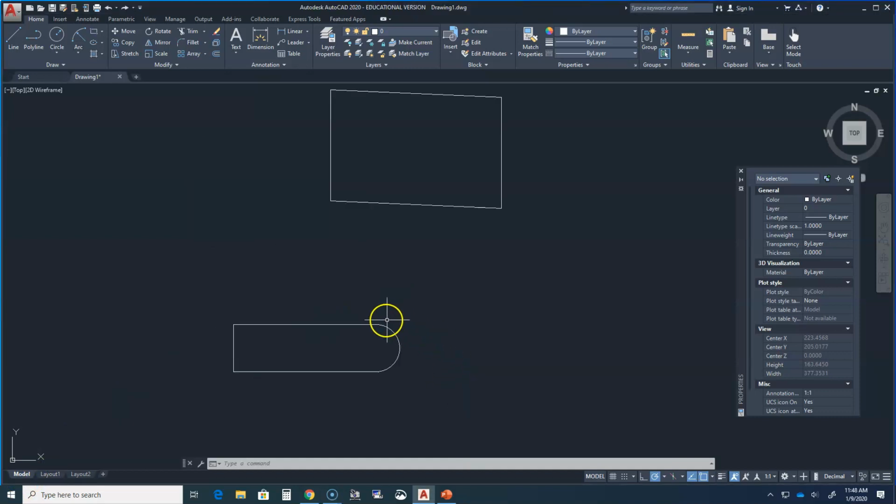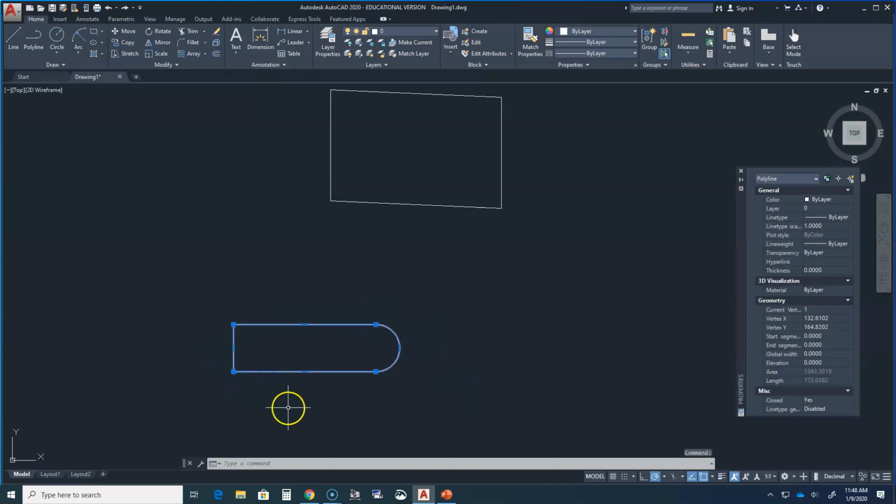Just like before, the geometry is all one piece. Select it and you will see that all of it illuminates. Hover over the linear grip in the far left closing line and wait for an options menu to pop up. Select Convert to Arc from the menu. Adjust the arc until it matches the arc at the other end. Then left click to terminate the operation.